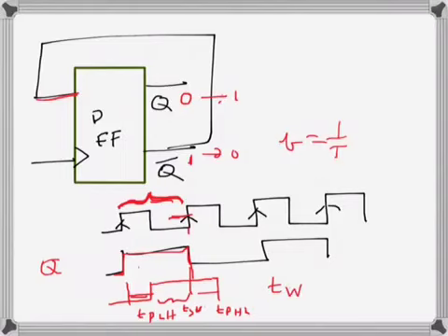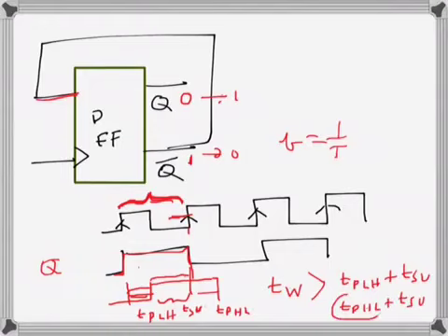TW, if we call it, has to be greater than the TPLH plus T setup time. This is the delay and this one is the setup time, so the addition of these two we have to accommodate before the next clock comes. So this one, or TPHL plus TSU, as we saw in the last video, these two can be different, so whichever is bigger has